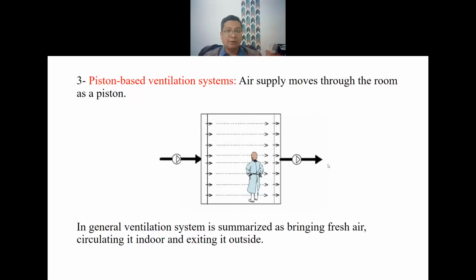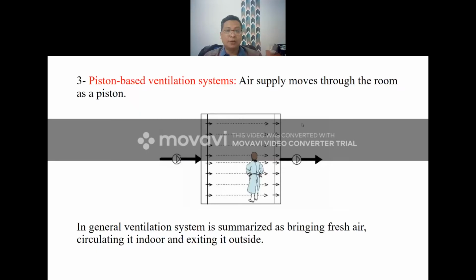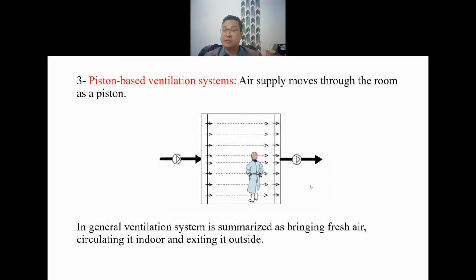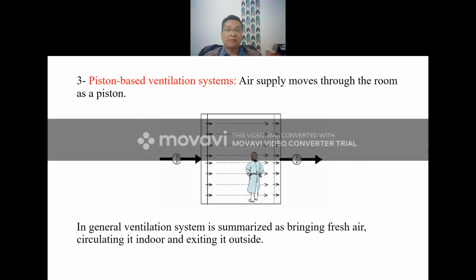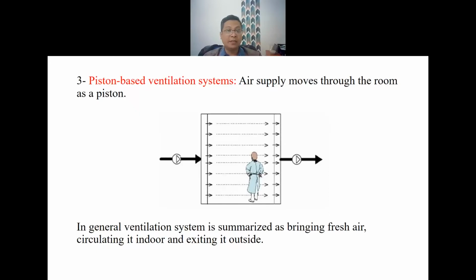So it looks like this, where we supply the air distribution like this. It will be distributed in the room, with similar pressure inside, so the pressure condition will be homogeneous inside, and outside the room there will be another pressure condition. As we know, if we have two different pressures between one zone and another, there will be a flow.